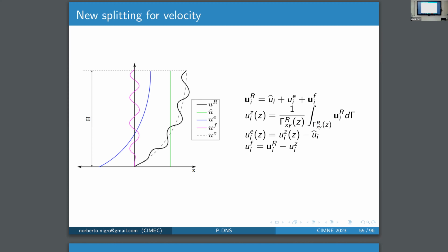So with this simulation, we have to move with another splitting, like I said before. The splitting now is this. We introduce this enrichment velocity, because close to the wall, the profile of the velocity is curved. It's not linear. The contribution of this curvature is very important, especially if you think about Nikuradse profiles or Blasius profile or slit profiles that use 1/5, 1/6, 1/7 power profiles for the velocity. The velocity u over u infinity is proportional to delta to the power 1 over n, with n equal to 5, 6, 7. So this kind of profile is not possible with a linear assumption for the RV.